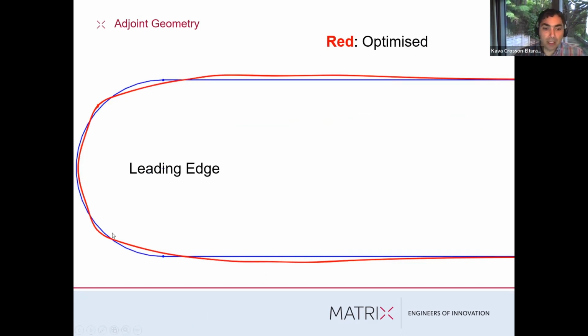You wouldn't have to introduce that wrinkly sort of 3D nature to it if you didn't want to. It'd be interesting to test out the effectiveness of having a constant profile with this optimized slice shape, because all of the slices were roughly the same in terms of this shape. They just looked wrinkly when you look at it in 3D. So that's an example where you can interpret the results and simplify them and probably still maintain some benefit there. But again, I think the benefit might drop off more quickly than you'd expect if you simplify the geometry, or if you go for a relofting approach where you reloft the surface and leave out those finer features.